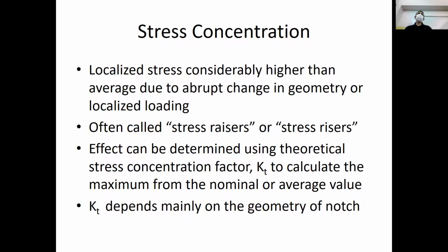The stress concentration in rare cases also could be due to localized loading. Usually the loading is distributed over an area, but if you have a very localized loading, yes, that can call for a stress riser, but primarily due to abrupt changes in geometry.